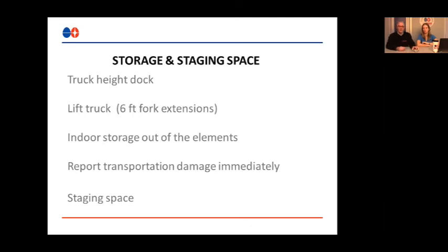a staging space near the bank is preferred. To add to that, if you are receiving HVAC equipment from Jamesway in terms of rooftops and chillers, that sort of stuff can be stored outside, but it needs to be stored on level ground, preferably a pad, not out in the grass or in unlevel areas, because what we have seen in the past is that storage in these sort of areas, some damage has occurred to the equipment. So keep that in mind as well.